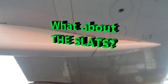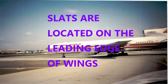Now, what about the slats? They're very similar when we think about flaps and slats. But slats are not on the trailing edge, they're on the leading edge of the wings. They're also a high lift device, creating an aerodynamic surface on the leading edge. They're also reducing the stall speed. They're retracted normally so that they're not creating a drag. Obviously, when they're deployed, they create drag.